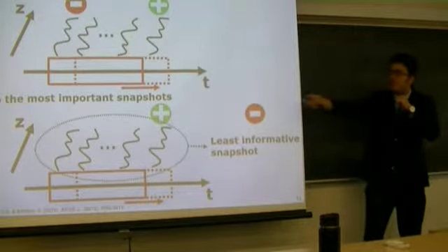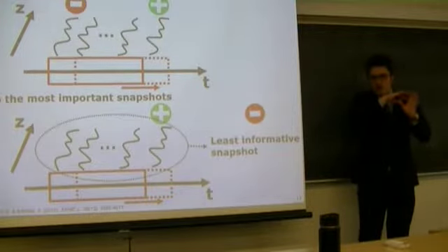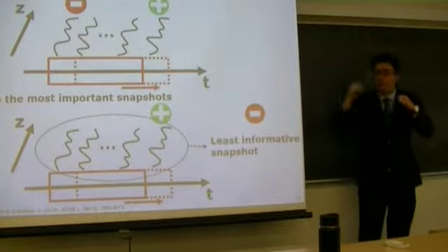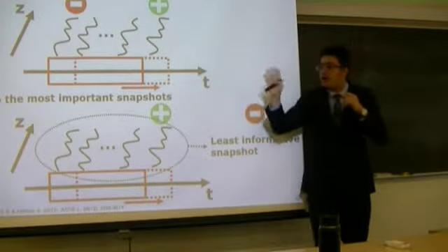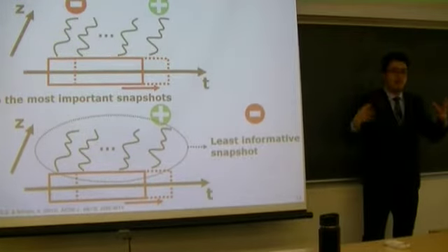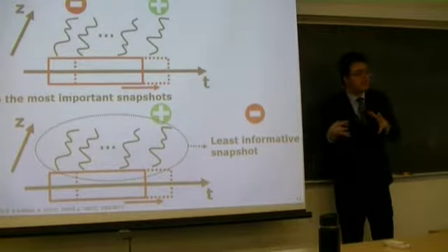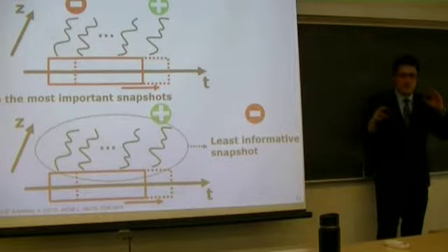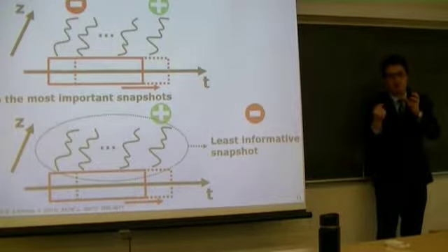So that means if we use this simple technique, when the controller has passed the transient behavior, we could not keep that important information contained inside the reduced order model, since we are repeatedly throwing out the oldest one and keeping the newest one, which may not contain enough information to represent the system. So for such cases, when we have a disturbance in the middle of a stable behavior, the controller is not aware of the disturbance until it gets feedback from the process.